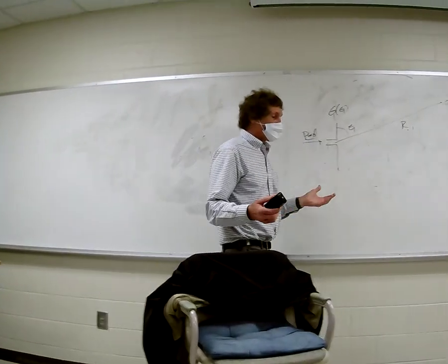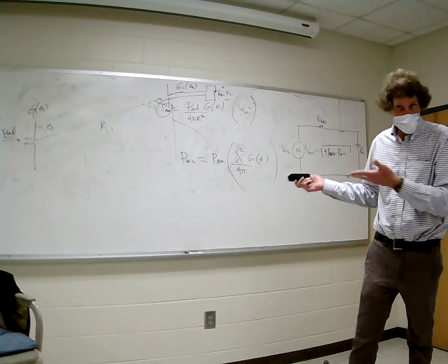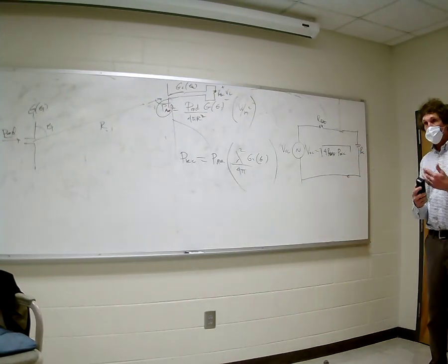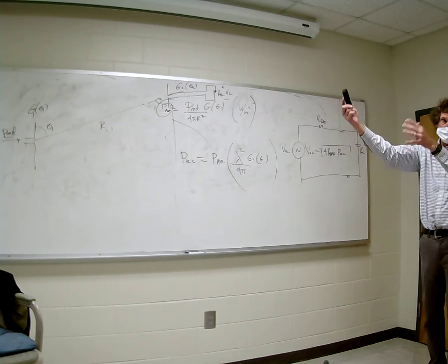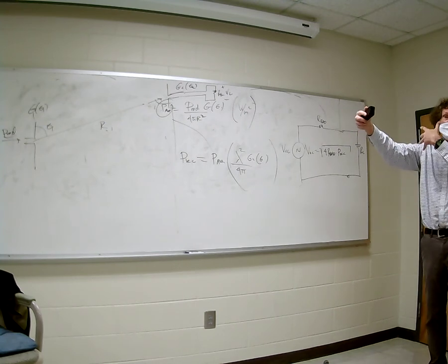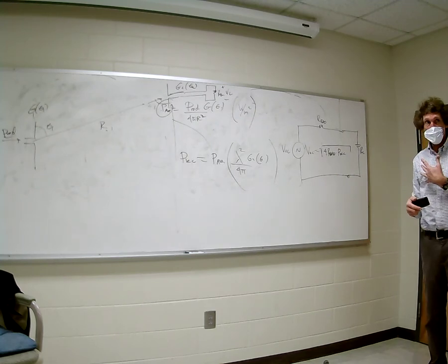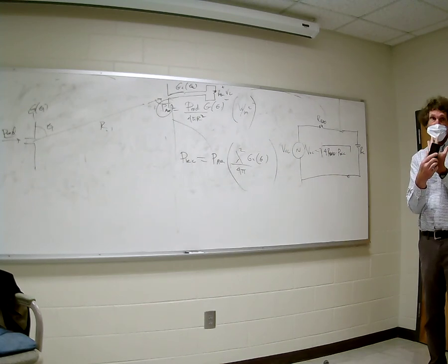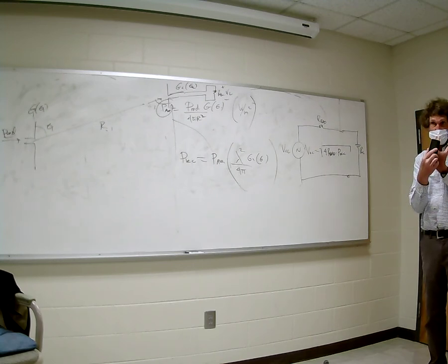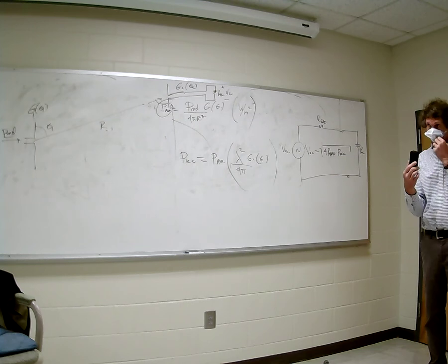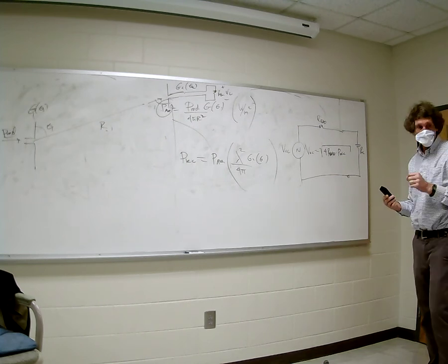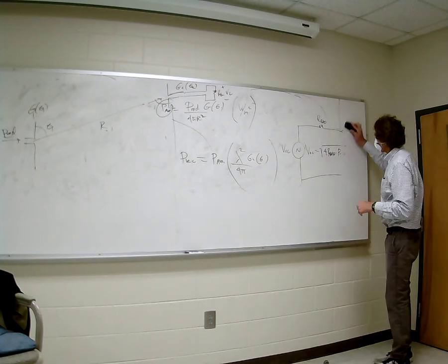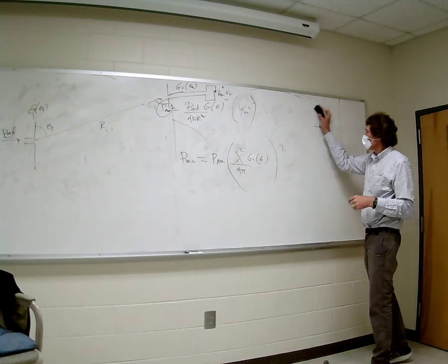All right, now, so we've gone through that. We've gone through the Friis transfer. That's basically Friis, what I just did. We've gone through radar, power launched, hits something. The size of it determines how much power is reflected. That power reflected falls off as 1 over 4 pi r squared again. That's the power density back at the radar. If we want the power received by the radar, now we multiply it by the area of the radar, which would be lambda squared over 4 pi times the actual gain of that antenna. That's a simple way of doing it, but it's effective. And you'll find out that little bit of information will get you a long way when it comes to coming up to speed with radar.